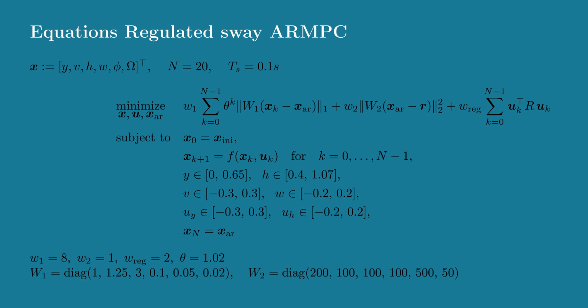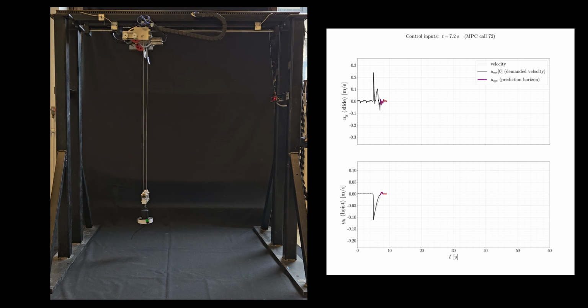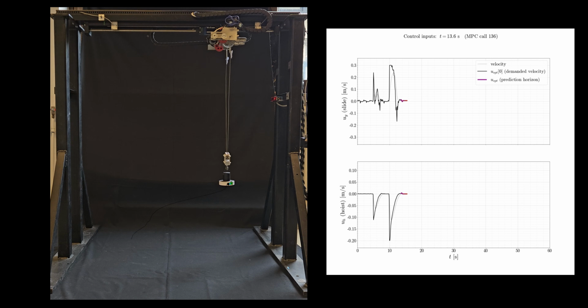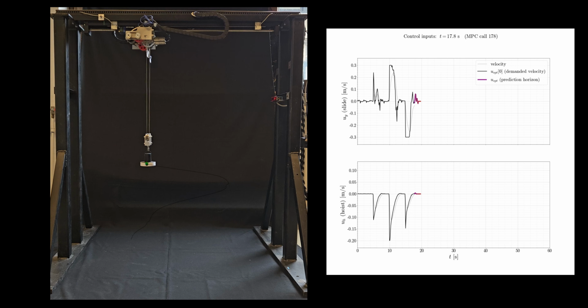This L1 structure tends to produce bang-bang inputs, saturating at the limits, rather than moving smoothly. Let's see this on hardware. The starting position and target are the same. The payload still settles without oscillating through a different trajectory. Notice at the end of the prediction horizon, that is, the artificial reference, converges smoothly to the target state.